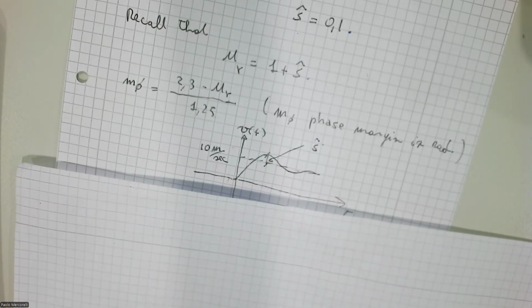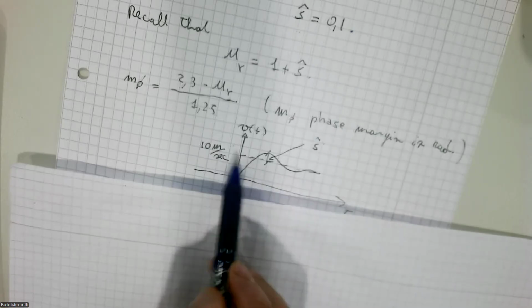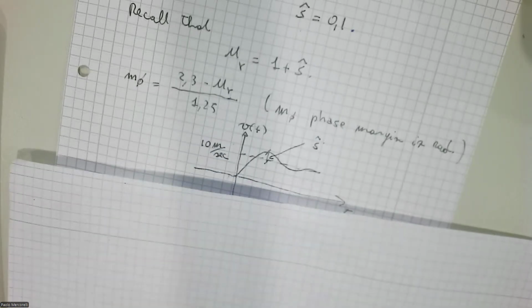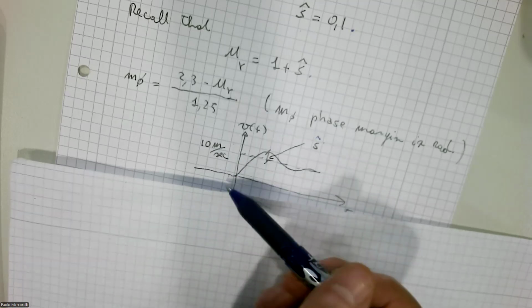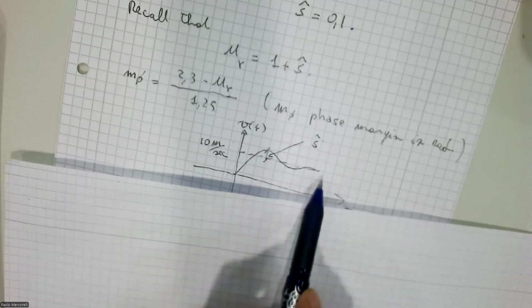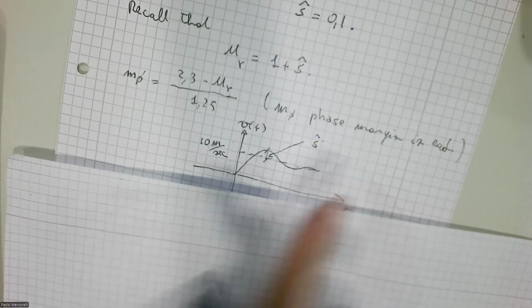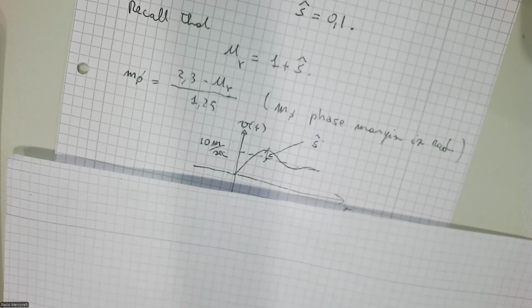Really, please pay attention. We apply the step, but we design the controller considering Ki related to the ramp. This means we will follow the ramp, but we will break thanks to this signal, which is limited. I don't know if it's clear. This R of T is a design signal, which is not applied. The step is applied. I mean, you push and you accelerate.